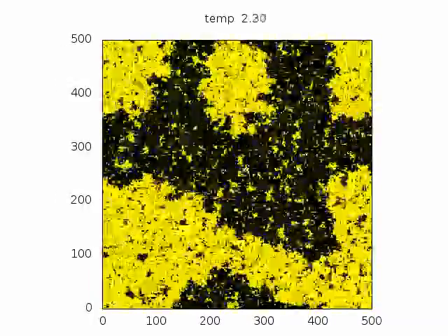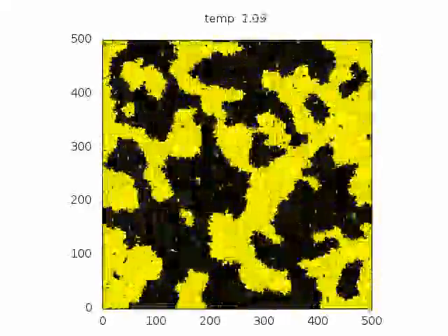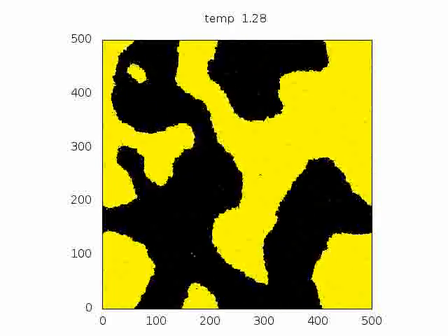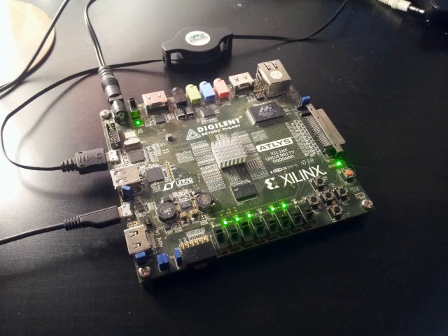The problem is that to make the video you see, it takes a lot of time on a normal computer, as we have to play this flipping game for a long time before we see any blobs forming. But as the Ising model is very interesting to scientists, we want a fast model so we could learn more about the physics inside. As each site only depends on the state of its neighbors, we can update many spins in parallel. As a normal PC has only one processor, I programmed this model on an FPGA where I am able to do many updates of spins in parallel.